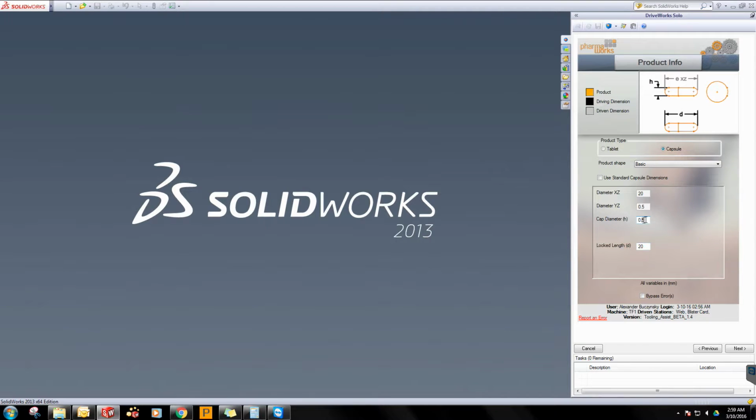That's pretty much similar. Now if you had values that were very close, so let's say this one was 10.36 and 26.4, let's say we went with something like 10.3 and this was 26.2. This will automatically suggest a capsule size, which is very nice because if somebody doesn't realize that there's already a standard size, the designer will automatically get prompted by the program to go ahead and select that. And if I do, it'll select that standard capsule size.